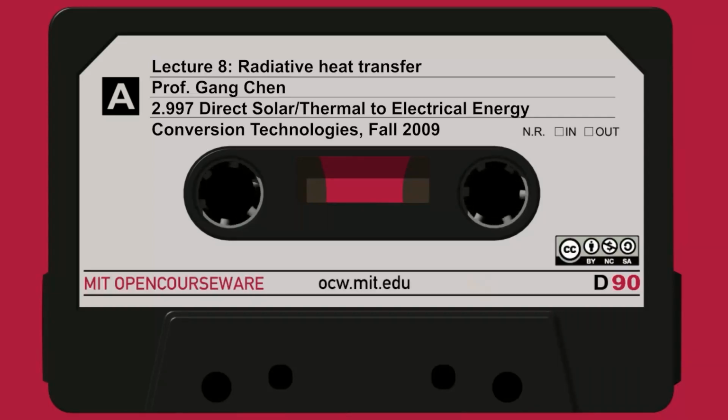And then, going back to the definition of intensity, this is the power in the cone times the solid angle that this area dAj subtends with respect to this point here. That's dAj cosine theta, the projected area, divided by r squared, the distance between the two surfaces. This is the power in this cone reaching that area.